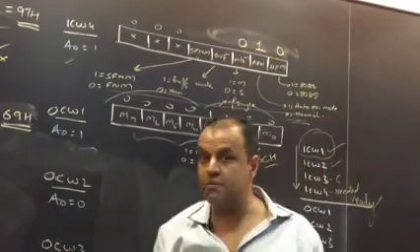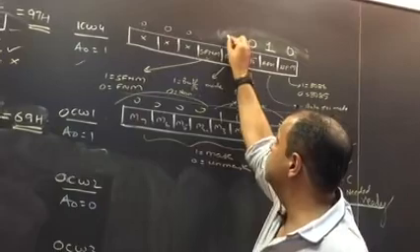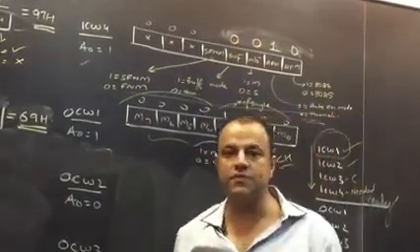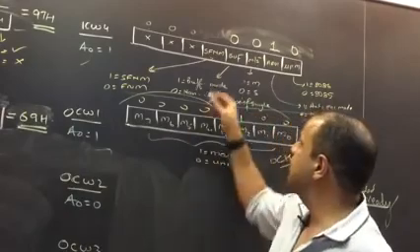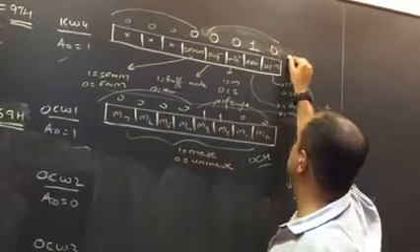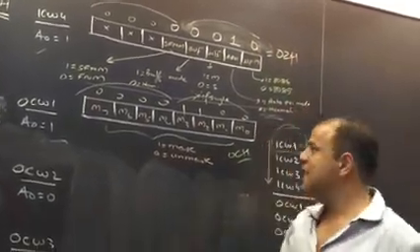Buffered or non-buffered. Remember, 8085 circuits are non-buffered. Non-buffered is the default option. Since they have not interfered with it, you should also not. Same goes with FNM, SFNM. SFNM is never used in single. SFNM is created for cascaded 8259. So this bit will be 0 because it is single. So the number is 0. This number is 2. So your total number is 02H. Are you clear? 02H is your command value.